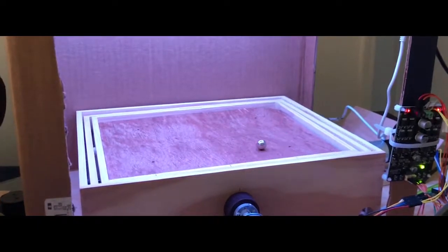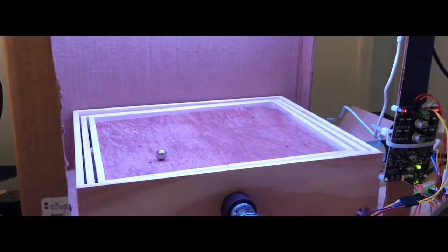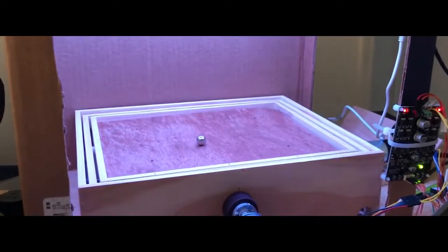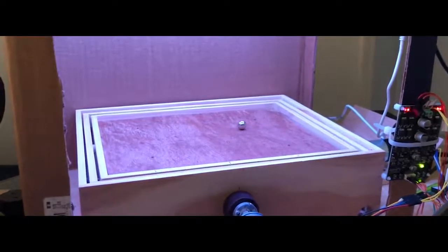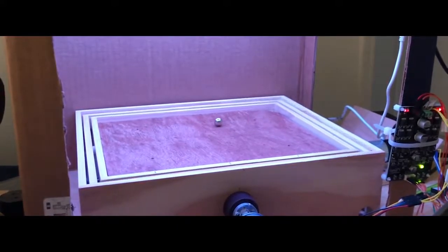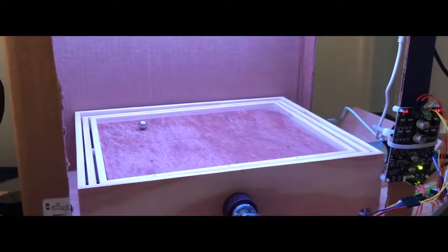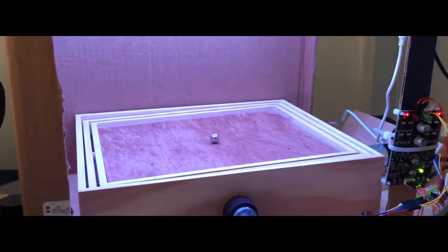The gear motors have optical encoders to determine the rotation of the motor shaft. The encoder signals are fed into two quadrature chips which increment or decrement based on the direction that the motor is turning, and the total count is then fed into the microcontroller to be used in our motor controller.